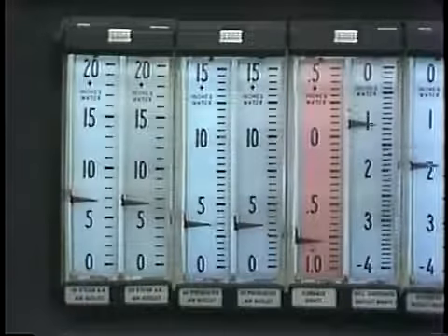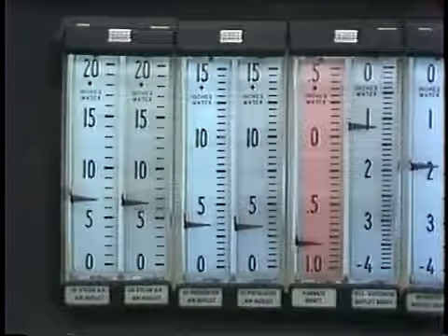A flameout will also upset the flow of air and gas through the boiler, sometimes making balanced draft boilers go positive or pressurized boilers go negative. An operator can monitor this on pressure gauges in the control room. One thing that you need to keep in mind, however, is that a loss of flame is not the only condition that can cause some of these changes. Also, it may take some time for these changes to be indicated on control room instrumentation. In most cases, it is best to use visual indication as the primary means of verifying a loss of flame.